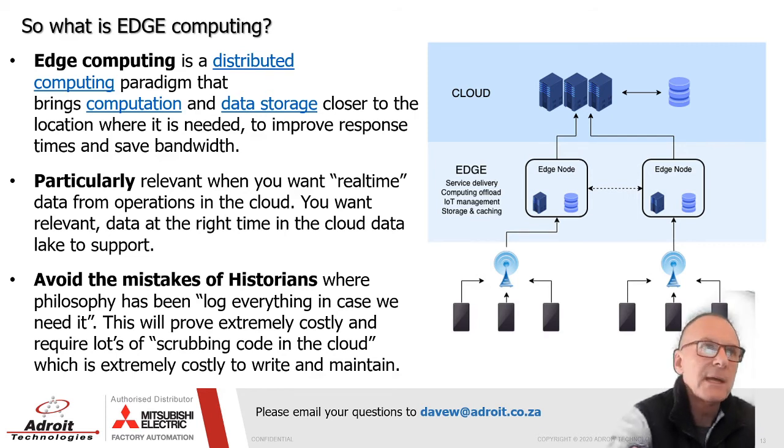You want to maybe take once every half an hour, take the snapshot and put it up. At the same time, if something's changing a lot, you may want to just take the average. If a speed is varying very quickly and a lot, maybe the average speed is important. So average it at the SCADA level and put the average up into the cloud.